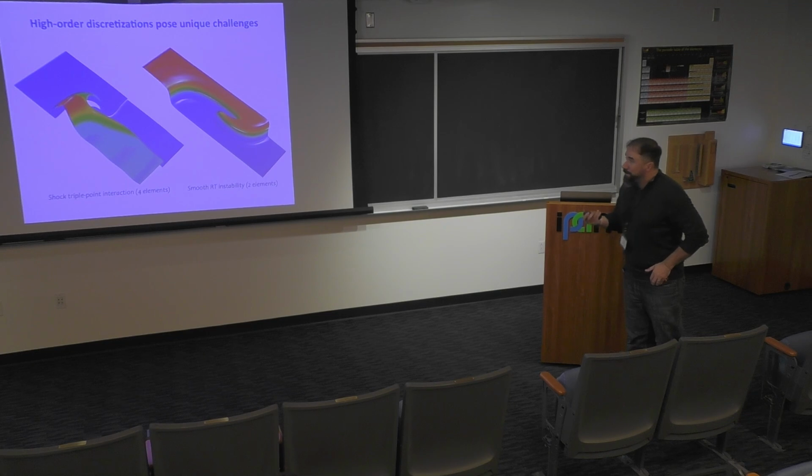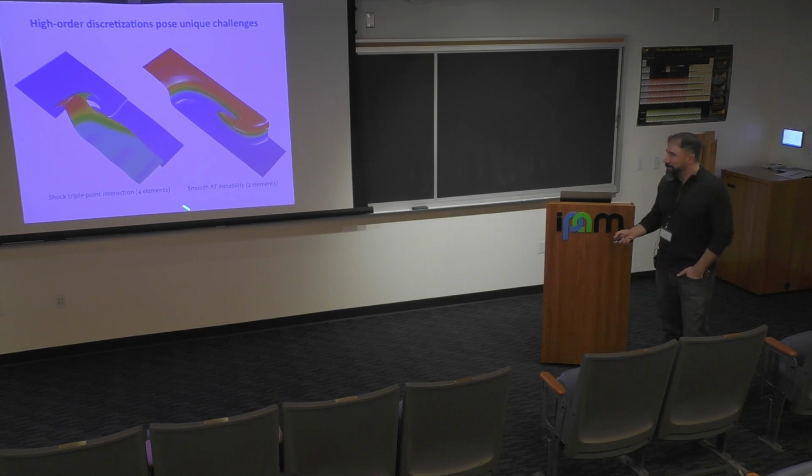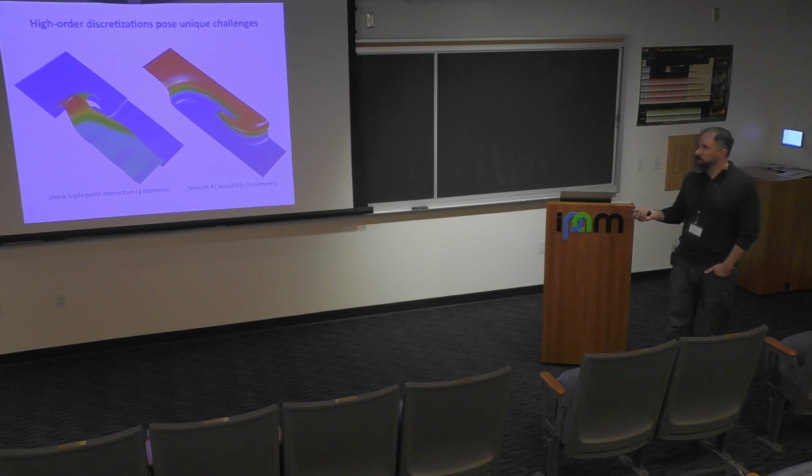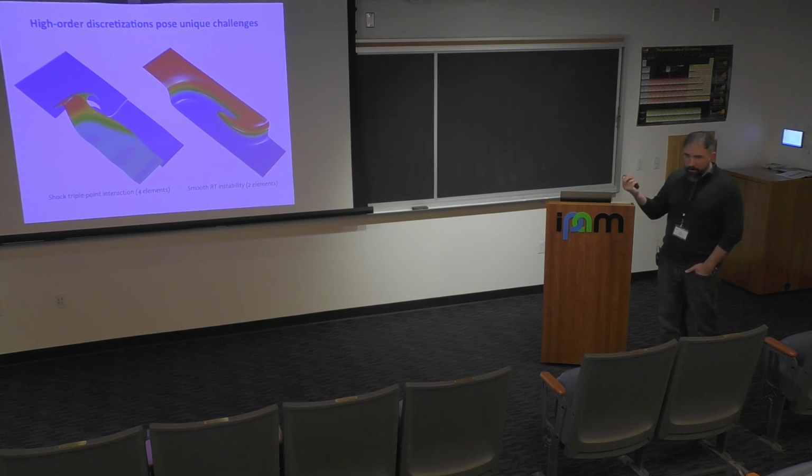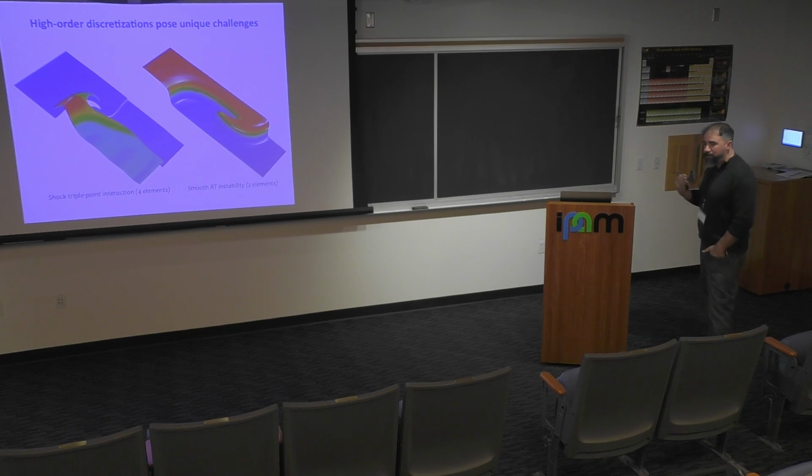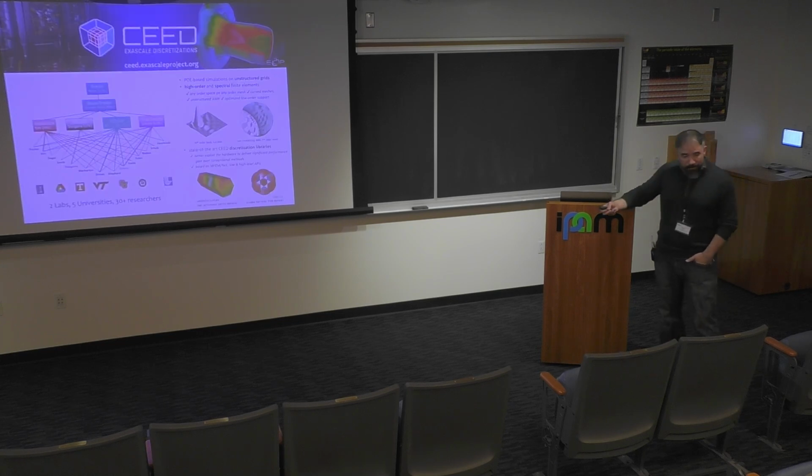So there are a lot of very delicate changes to physics algorithms that need to happen. That's one. The second thing is, again, related to HPC. All degrees of freedom in this element are fully coupled. And so it becomes extremely expensive. It's very easy to have algorithms that are O of p to the 9th, where p is the order. When p is 10, that's 1 billion flops per element. You cannot afford that. So the other thing is that you have to be very efficient. And improving application algorithms and efficiency of high-order methods have been the focus of this co-design center.